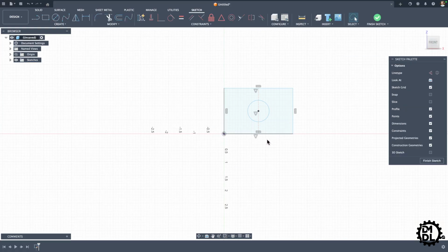Okay, so those are 2 of the most basic ways to create some sketch entities. Let's go through a couple more. If you want to get a bit more creative, you can use a fit point spline. In this way, you can click basically where you want that spline to start. Then you can click a few more points that allow you to control the curvature of that spline.